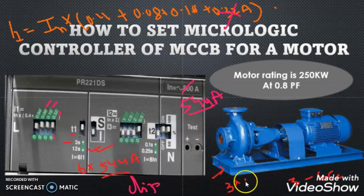Our full load current is 544 ampere. The breaker will hold this current till 3 seconds if the dip switch is up, and till 12 seconds when the dip switch is down. By that time, the motor starting current will vanish and the motor will take only full load current. So the breaker will not trip, as the starting current vanishes before the 12 seconds.